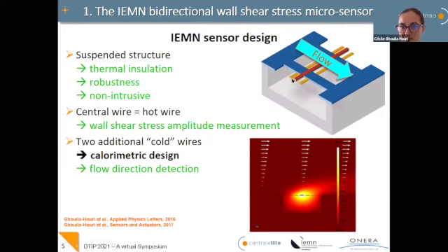On this schematic, you have in red the hot wire, where we have the heating current, and under this hot wire, we have a yellow wire, which is a measurement wire. We have a very thin layer of silicon oxide between them to electrically insulate them. We use the measurement of this yellow wire to adapt the current in the red wire. It's just to improve the signal to noise ratio by uncoupling heating and measurement, two different circuits.